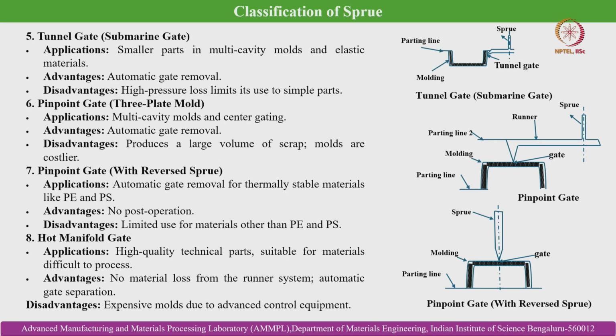So, moving further, now we will discuss the tunnel gate. You can see this configuration, and you can understand from the name itself. It is basically connected into the mold cavity slightly below the parting line, and hence it is termed a submarine gate or tunnel gate.